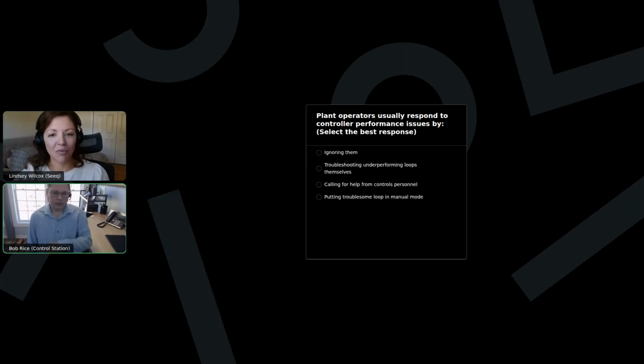even tell anyone, right? One of the interesting metrics that we tend to track is operator interventions: how many times they're putting it in manual, or making adjustments to the outputs while in manual, or set points, to try to bring the process under control. And that just shows a lack of faith in the controller being able to do its job, right?